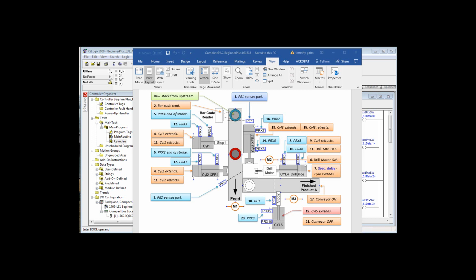Now, you could put a centrifugal switch on the motor, and when the motor comes to a stop, the switch closes and says it's no longer rotating. But that would be a waste of time and money to add to this kind of process. So number 12 turns out to be another action. And that other action is that we're going to retract cylinder 1 and cylinder 2.